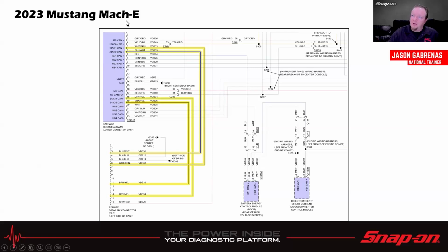I'm not an electronics engineer by any means. I know just enough to be dangerous, I guess. As an example, on a 2023 Mach-E, as you see from the diagnostic connector, it's diagnostic CAN. So it's still regular CAN. But then I see up here, I have high-speed CANFD, and I have high-speed CANFD right there. So it has CANFD internally inside the vehicle through the gateway module.